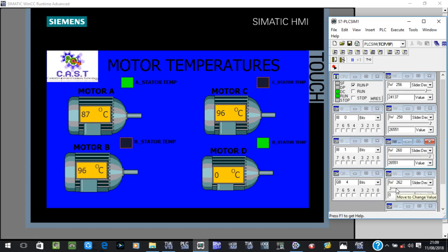this is all designed within the program like I showed before. I have to change here again my standard engineering value, 27648. Enter. That's my maximum value. Now I have to go again. 256, 258, 260.